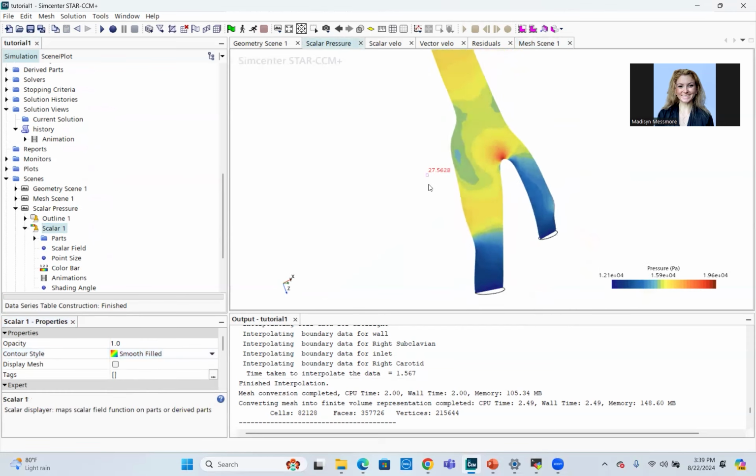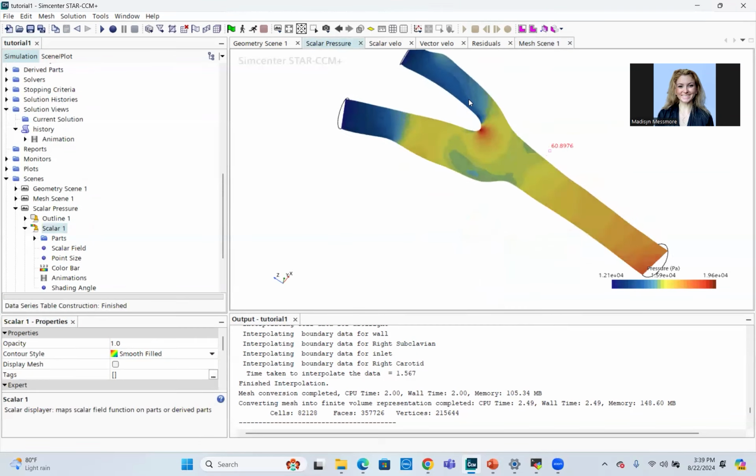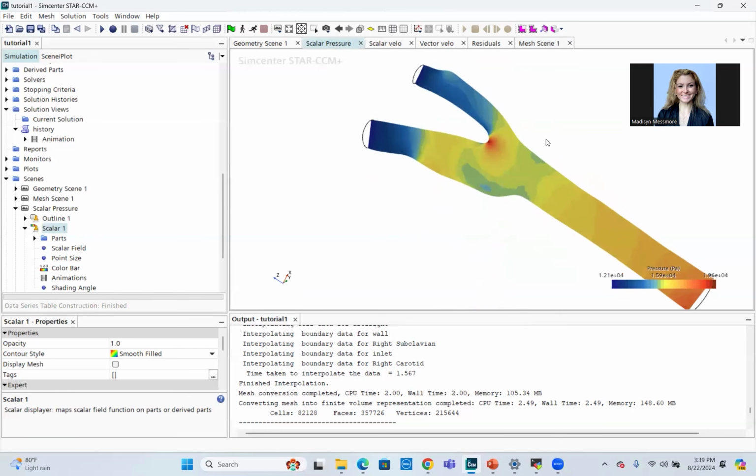Yeah. But honestly, you always should do a grid refinement study, just for good practice, even if it is annoying and it means you have to run your simulation 3 times. That's what it is. Yeah. Any other questions?